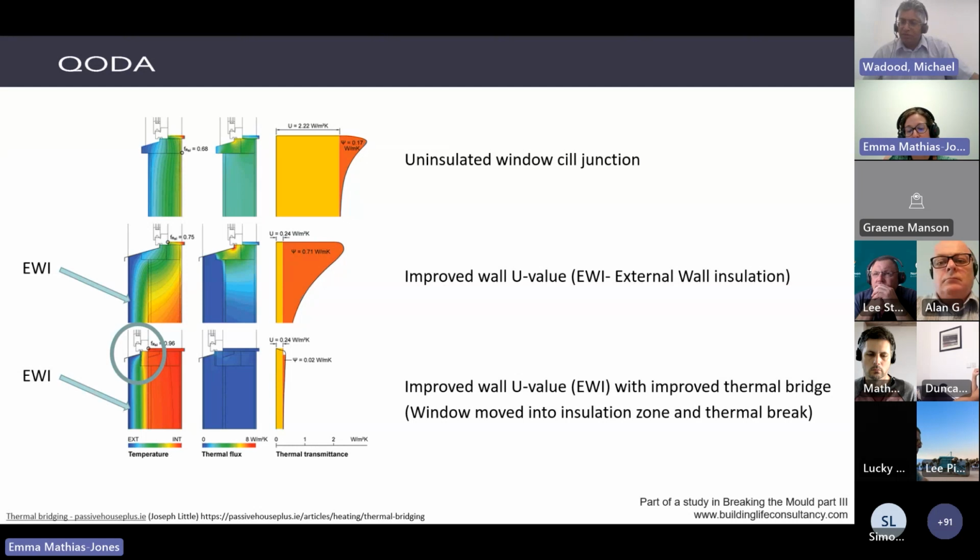So would that actually be reflected in the EPC rating? Because really, if it followed all the U values and was designed to the U values and they air tested and produced the EPC, and the EPC was of a value B, that wouldn't show the deficiency in the thermal bridging that has occurred. Yeah, so it's often part of the performance gap. That's probably a negative point of just following what's in Part L, the U values, and testing it by focusing on one item.